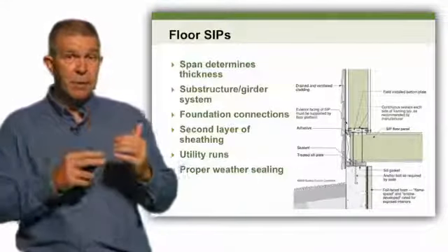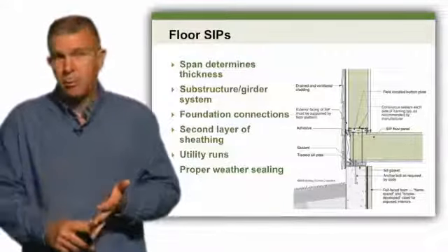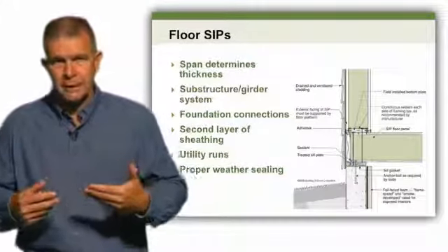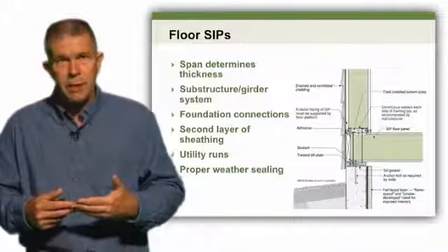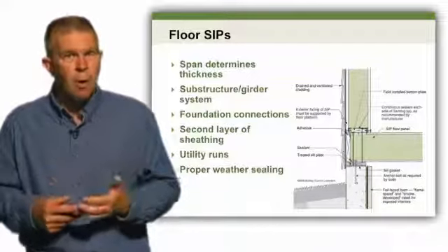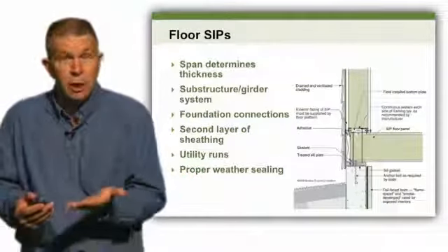That's why at the very beginning we talked about small additions and working up on top of pilings where floor SIPs really make sense. This is where we want to go through the extra effort to protect them from the weather so that we can utilize them and not worry about weather or moisture related concerns for a horizontal floor that can potentially hold water.